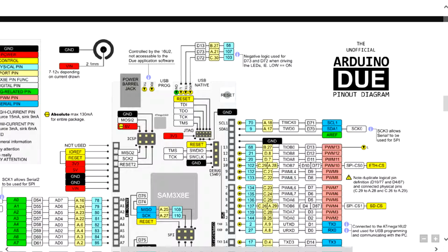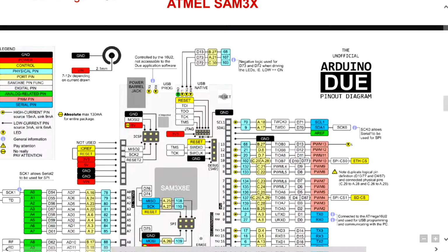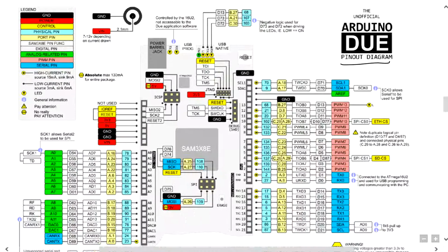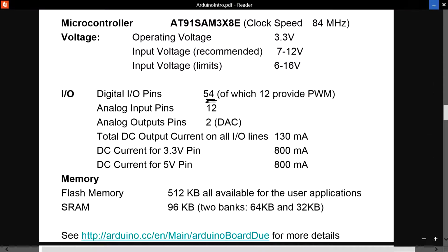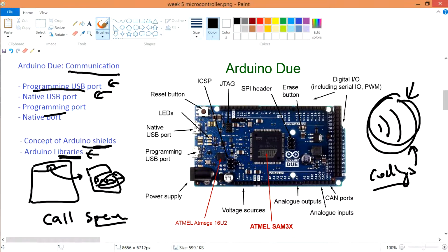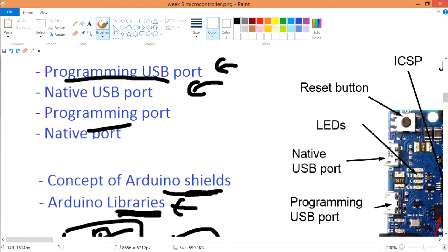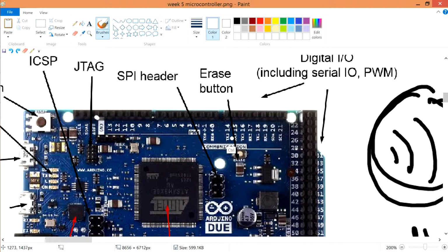And inside your PDF, you are also given your pinout diagram. Your pinout diagram tells you which pin does what. Alright, in total there are 54 pins. What are the 54 pins? These little things are all pins. If I zoom in more properly, these are all pins. The 1, 2, 3, 4, 14, 26, these are all pins. There are 54 of them.